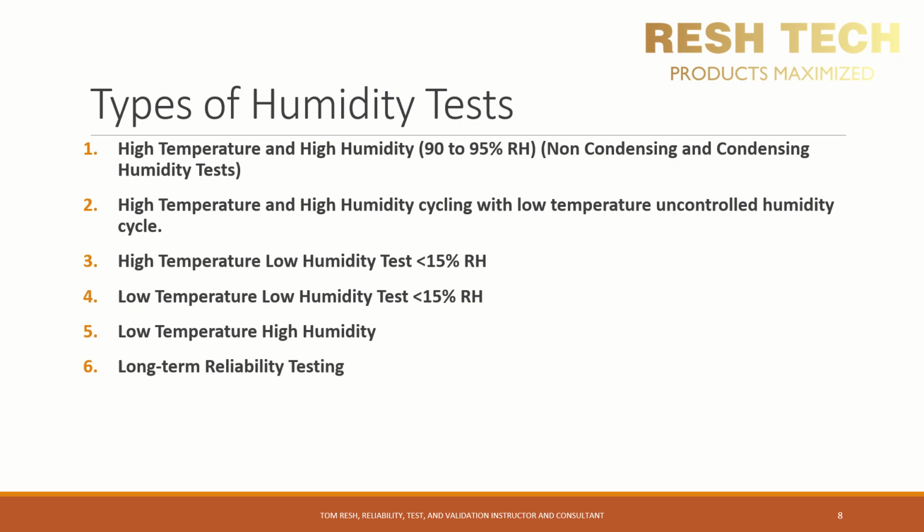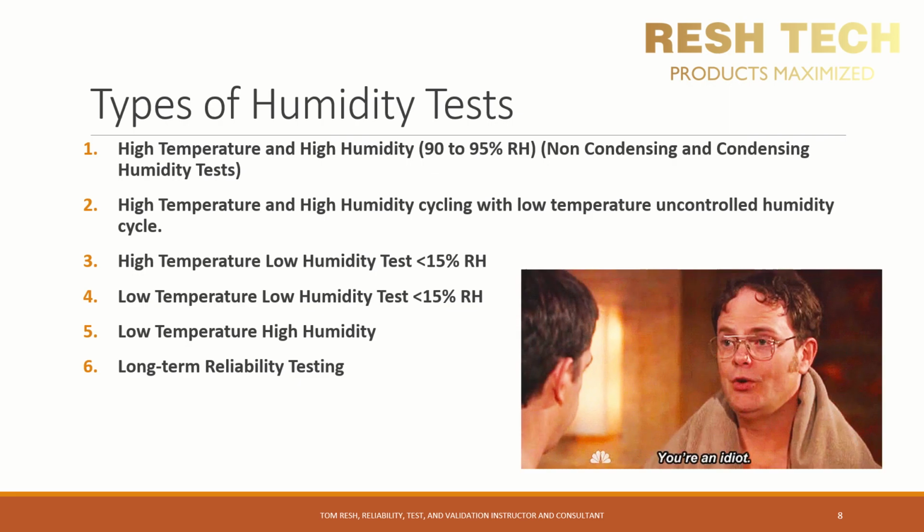Another type of test is the low temperature and high humidity test, which I do not recommend running with a conventional humidity test chamber. If you're trying to create snow here, get creative and go buy a snow machine and use a freezer. Don't try to run high humidity and low temperature in a temperature humidity chamber, as you can damage or incapacitate your temperature humidity chamber. So don't be an idiot.